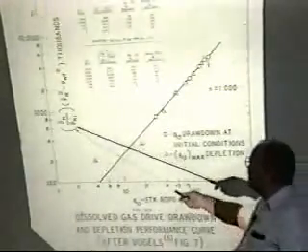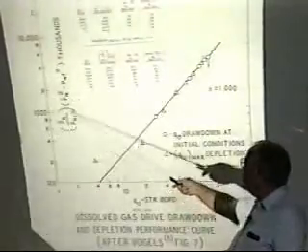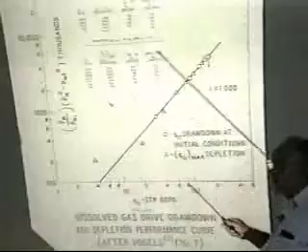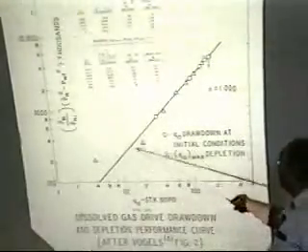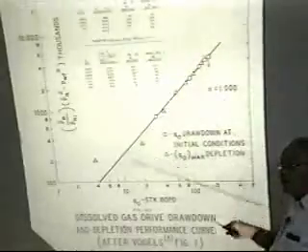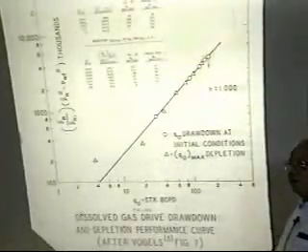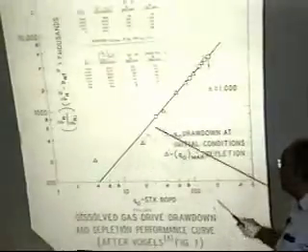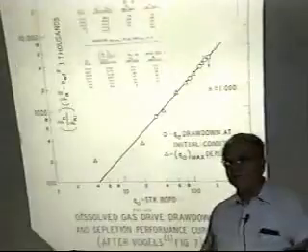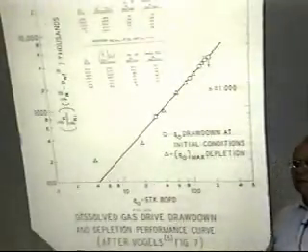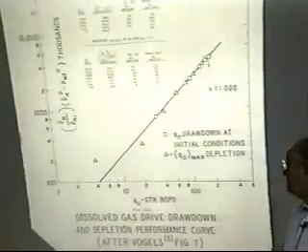If you take all of Vogel's data that he published, and even that other paper, and you use this form of equation, all of those curves that were shifting down with depletion can be represented by a single back pressure equation that includes the effect of relative permeability. And again now, I've got a back pressure equation for an oil well. It includes also the migration of the performance curve with depletion.